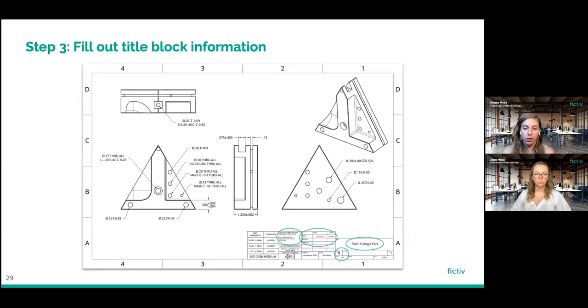So unless otherwise identified on the drawing, all units are in inches. So that's really good to know. All of these dimensions are in inches. And also good to know because we have a couple holes here where we did call out metric taps. So even though those are metric taps, we still want to know that the diameter itself that's called out is in inches because that is not called out any differently.